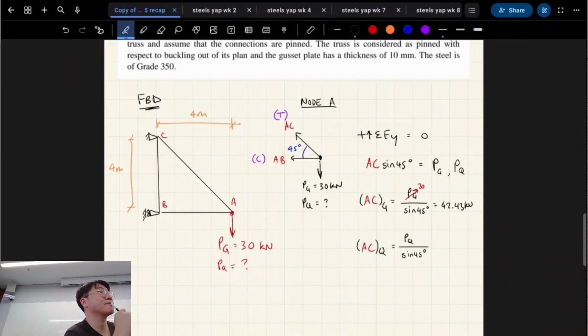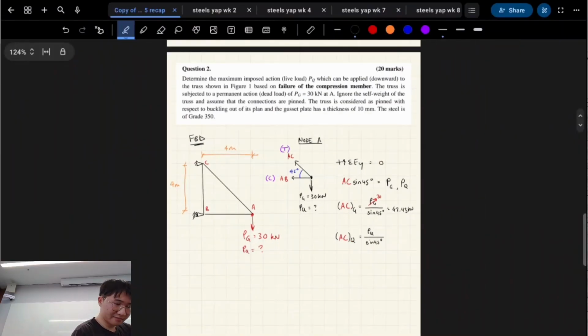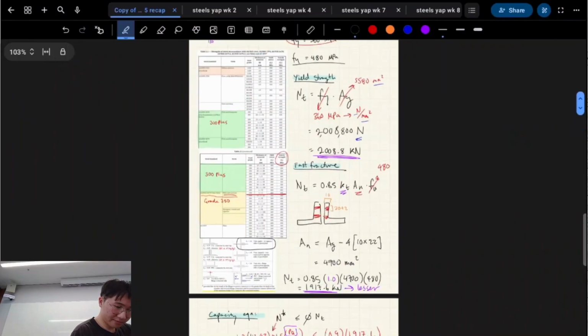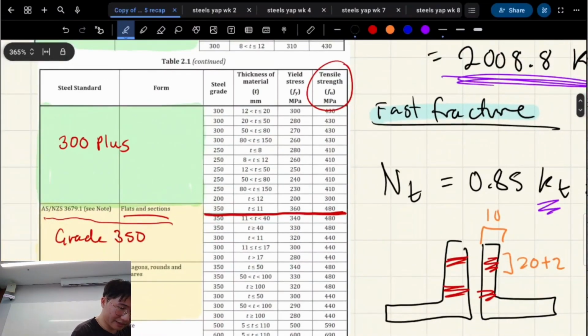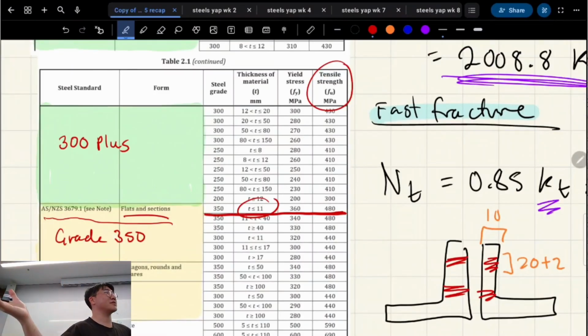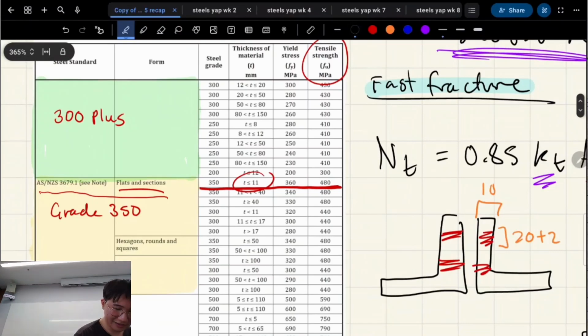It says T is 9.5. It says 10. T is equal to 9.5. Oh yeah, same thing. I asked, it basically doesn't matter, because the only thing that thickness actually determined was which range of yield strength we care about, right? So it's going to be the same ballpark, right? As long as it's less than 11, it doesn't matter, right? As long as you're using the AG value provided in One Steel, it'll be accurate because that AG accounts for the fillet and everything.